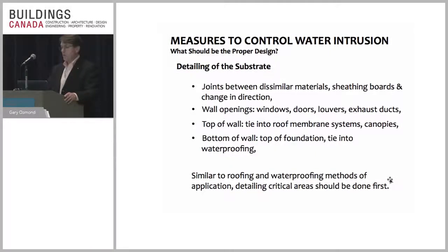So measures to control water intrusion is about detailing. It's not the field applications. Problems happen in the details. Joints between dissimilar materials, sheathing boards, any change in direction or change in material, wall openings, top of the wall: is there air able to escape through it? Have you tied the roof into the walls? All these types of problems, and certainly at the bottom, it's understanding what's happening at the foundation level and below